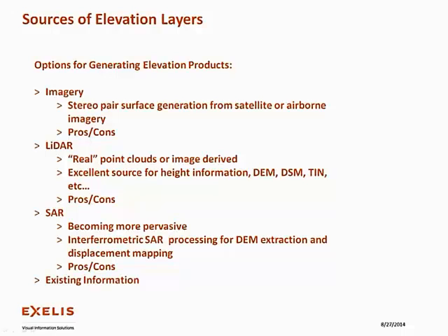LiDAR. So if LiDAR is available, you're getting, I have in quotes there, real point clouds, as opposed to image-derived, where the imagery is not only constrained to the spatial resolution and the surface features, but you also get a very regular grid with 1 point per pixel. And with LiDAR, you're getting a very irregular grid. Also, the density of the LiDAR point cloud can be variable, and you can get, in most cases actually, a much higher resolution surface derived from LiDAR. Some of the excellent sources for height information are DEM, DSM, and TIN.